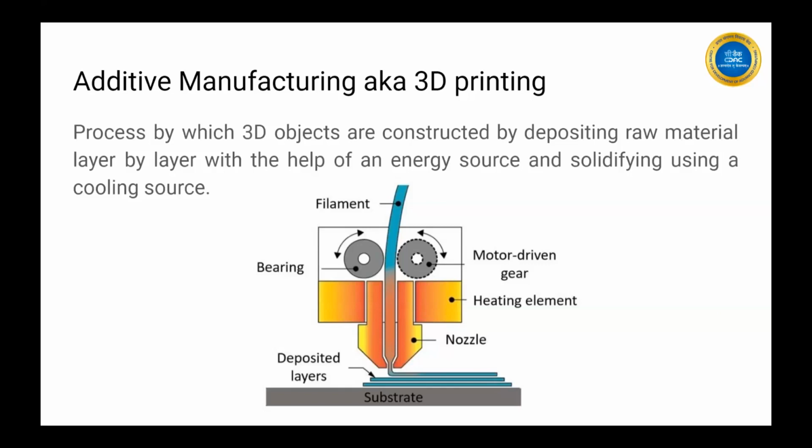Okay. Yeah, 10 micron to around 400 micron, up to that level of layer heights are possible in case of a polymer FDM machine. Okay, so it is printed, it is deposited layer by layer until we get the desired shape. Sometimes there will be some supports involved, but still the wastage of material is very less as compared to conventional and casting processes.